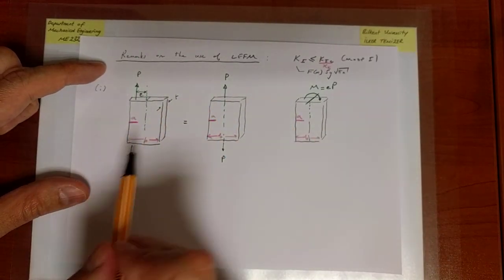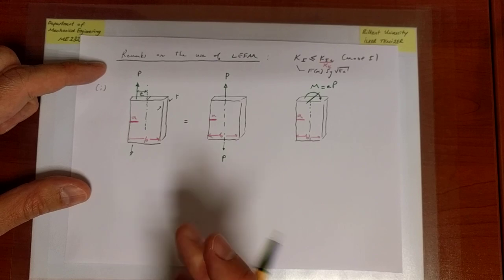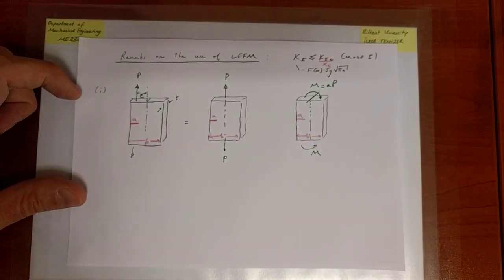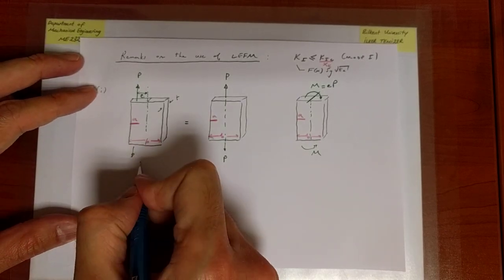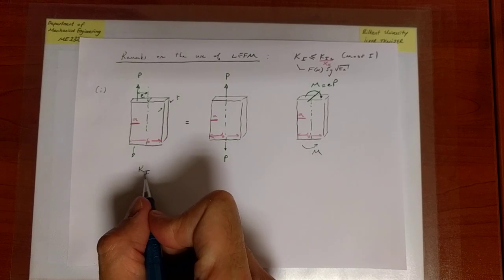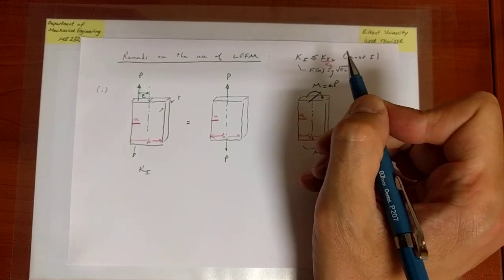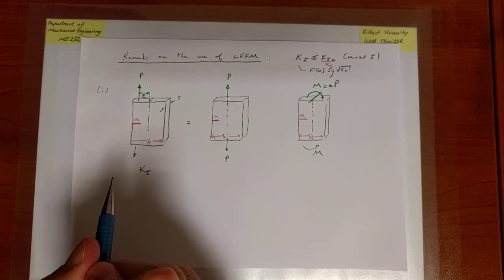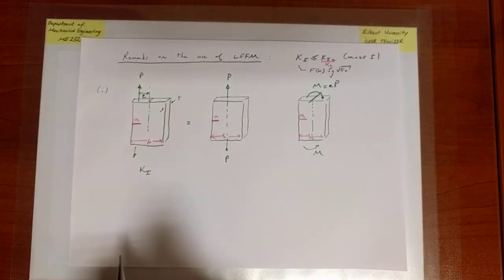But ultimately, that itself doesn't mean that we can ignore it. We should eventually, you'll see, consider it in combination with the tensile stress itself. So in this case, it's opening mode. I don't need to worry about the crack closing. So this bending moment is certainly going to be relevant. So now what I need is the value of K1 in this case. If I can calculate what the K1 value is, the criterion remains the same. I will compare it against the fracture toughness, possibly scaled by some safety factor, to decide if there is some critical situation or not. The problem is I don't know how to calculate K1 for this scenario, but I do know how to calculate it individually for that and that scenario.